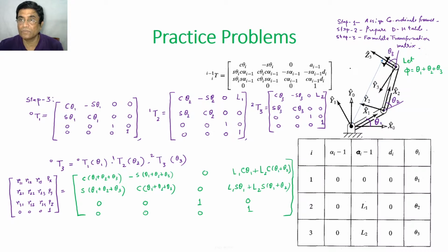What are the rules of assigning coordinates? Same as earlier. This is the 0th coordinate frame. Make the ith coordinate frame origin the same, so that most of the link parameters will be gone. So I have put our first link here.